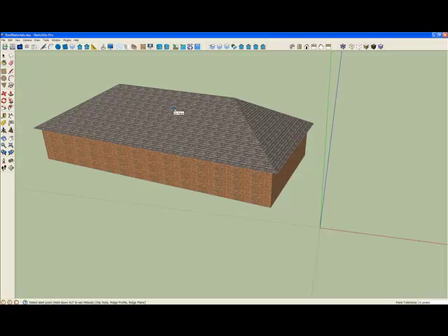And then when I do the second point, it'll tell me when that edge, the ridge line of the extension that I'm building, is perpendicular to the horizontal of that existing roof line. So that's useful because normally they are perpendicular, but once again, if you hold down the control key, then inferencing is turned off and you don't get that. But in this case, we want to be perpendicular to that edge.